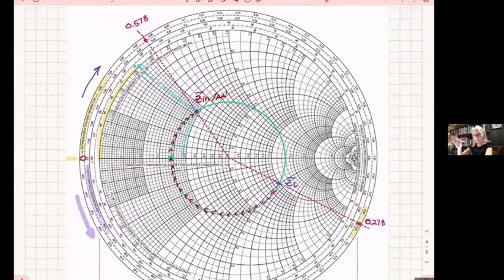Now, in this problem, if your load is on my right hand, now you see them reversed, I think, at least I do. I don't know how you see those, but if your load is on my right hand and then my source is on the left, and I move from the load towards the source, that therefore on the Smith chart, it shows along the yellow rim, and then says wavelength towards generator. And that's the direction I take because it shows me with an arrow the direction.